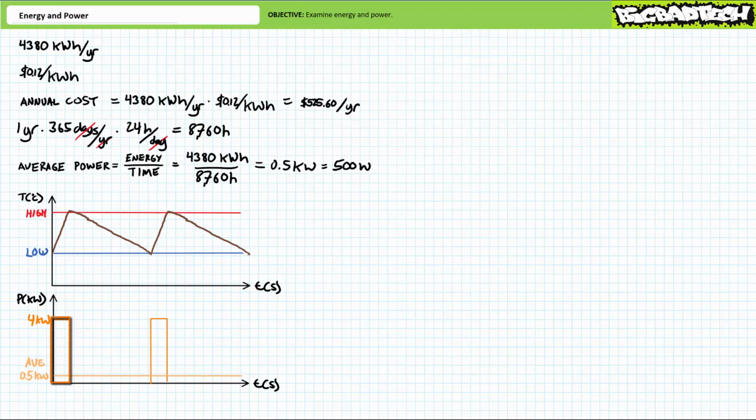In reality, we might expect a water heater to briefly consume massive amounts of power during the heat phase and then simply turn off during the rest phase until the temperature in the tank falls below the reset value. Obviously, water usage patterns would influence this periodic cycling. As a simplified illustration of this process, let's say a 4 kilowatt water heater operates on a 12.5% duty cycle, where for 12.5% of 60 minutes, or 7.5 minutes, the 4 kilowatt heater runs at full blast, and the remaining 87.5% of 60 minutes, or 52.5 minutes, the heater is completely off.